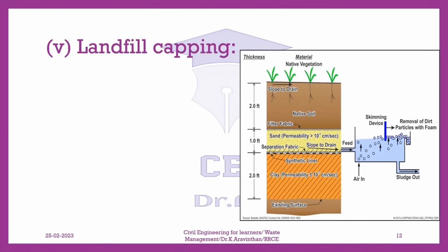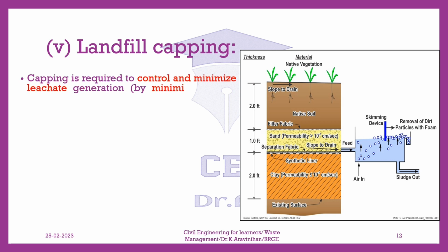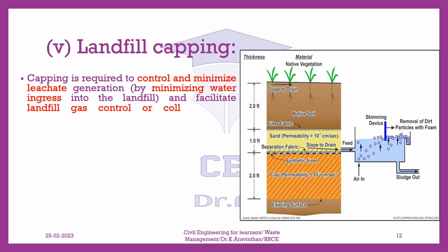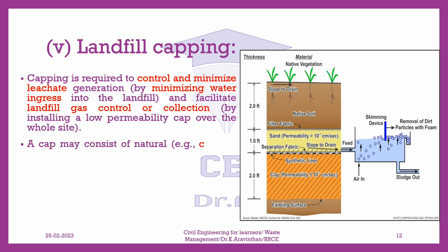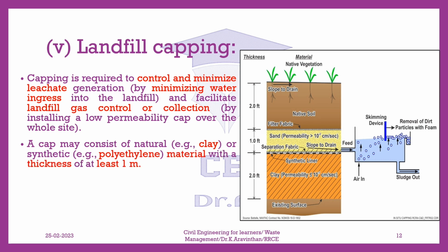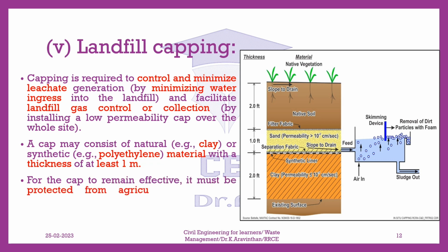Landfill capping. Capping is required to control and minimize leachate generation by minimizing water ingress into the landfill and facilitate landfill gas control or collection by installing a low permeability cap over the whole site. A cap may consist of natural, for example clay, or synthetic, for example polyethylene, material with a thickness of at least 1 m. For the cap to remain effective, it must be protected from agricultural machinery, drying and cracking, plant root penetration, burrowing animals, and erosion.